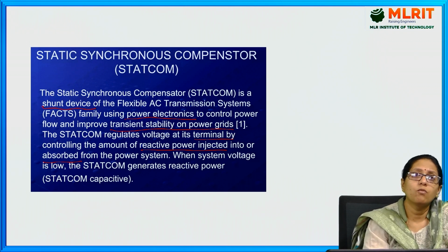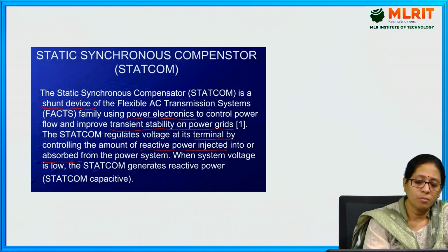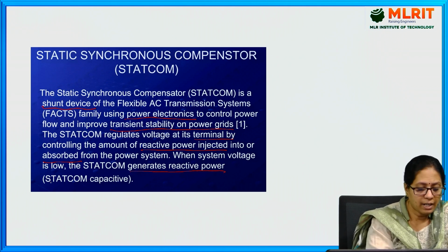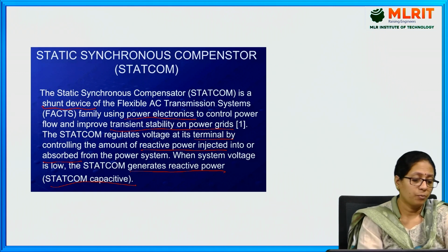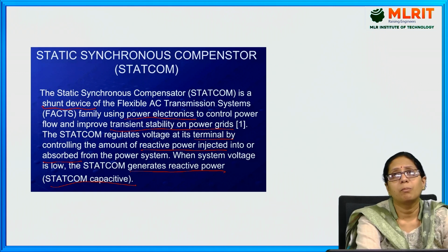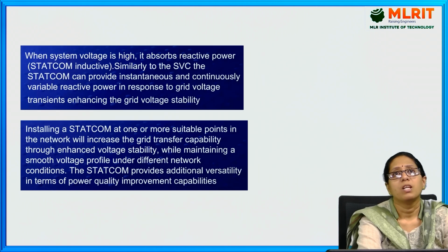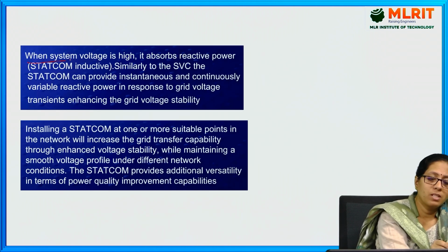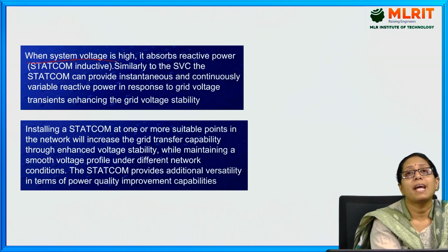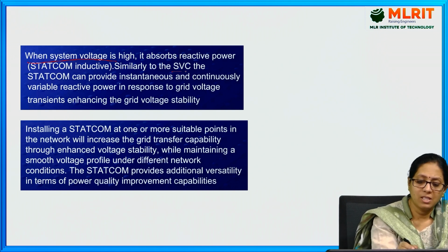When the system voltage is low, STATCOM generates reactive power. That is, STATCOM becomes capacitive. So this is another type of compensation. When the system voltage is high, it absorbs the reactive power, similar to the SVC.